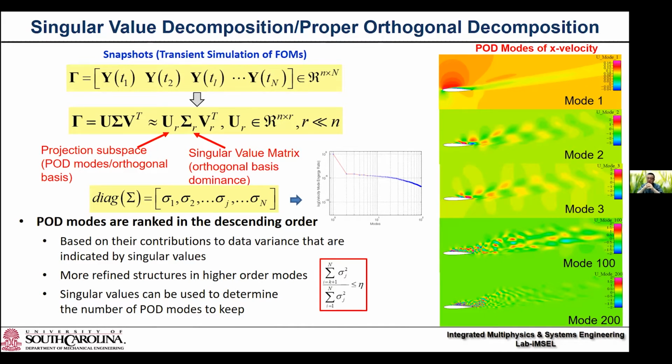All right. And the number of the elements in that single column vector is the dimension. For example, if I have 100 solution variables in this CFD model or finite volume model, then the vector will have a dimension of 100 by 1, right? Of course, I will collect a solution at different time steps, right? So this T1, T2, Tn will be the number of the time steps, and then you put them together. This is called a snapshot matrix.